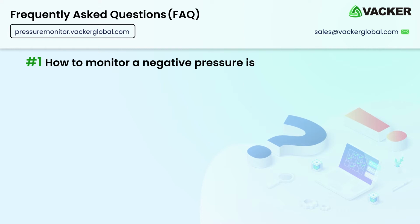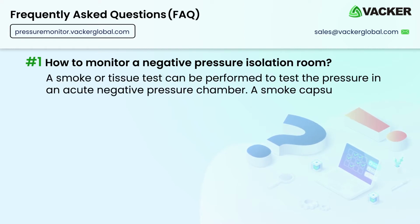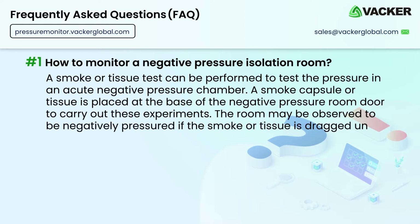How to monitor a negative pressure isolation room. A smoke or tissue test can be performed to test the pressure in an acute negative pressure chamber. A smoke capsule or tissue is placed at the base of the negative pressure room door to carry out these experiments. The room may be observed to be negatively pressured if the smoke or tissue is dragged under the door.